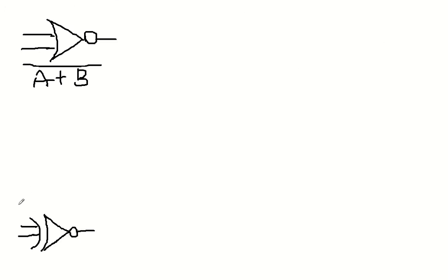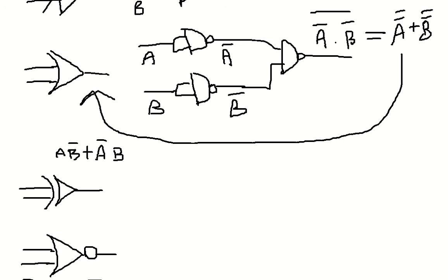So what was our expression for XNOR? Let's recall. Okay, AB plus A bar B bar. So now let's try to draw it.